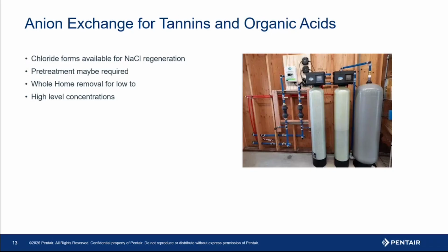You can use that same reservoir of salt. Pre-treatment may be required for tannin removal resins. Always check with your resin OEMs on the products they use for the information for pre-treatment, because that's going to impact your overall system design.